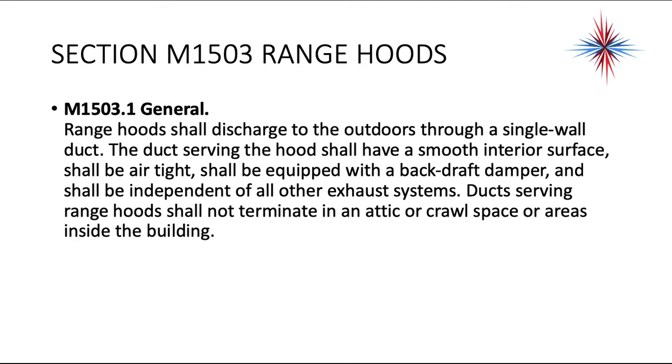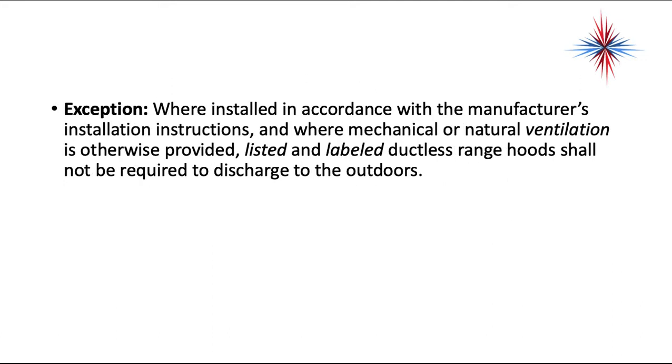Now the backdraft damper, again, if the equipment's not being used, we shouldn't be sucking air into the building through the greasy pipes. Okay? Backdraft damper opens when it's in use, closes when it's not. Now there is an exception. Where installed in accordance with the manufacturer installation directions, and when mechanical or natural ventilation is otherwise provided, listed and labeled ductless range hoods should not be required to discharge to the outdoors.